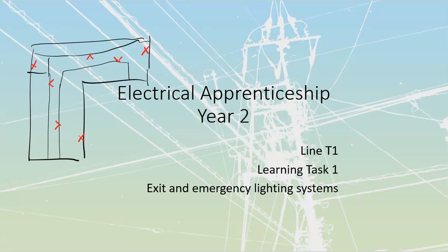Both of them are termed life safety systems, which means that we are going to be very careful about how we wire these things up. We don't share these circuits with other random stuff. We don't want these ones tripping out. We don't want problems caused by just the regular day-to-day life inside of a building somehow getting transferred onto exit and emergency lighting.